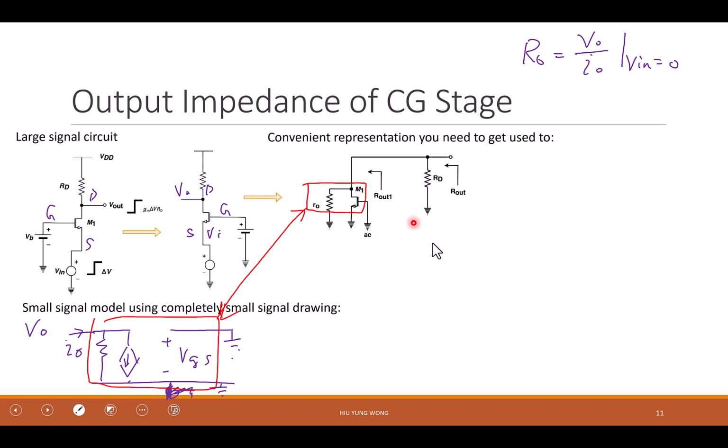Your circuit works by grounding everything? You know this is not the case because we are doing AC analysis. These are AC ground. In our mind, we already know that we have DC biased this transistor so that it is in saturation. We know there is a DC current, a huge current going through, biasing it also, right? But now we're just looking at the AC.